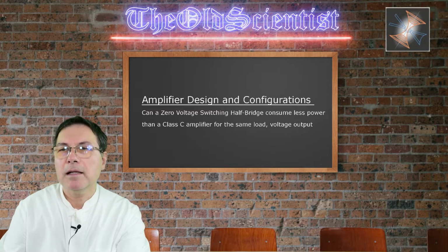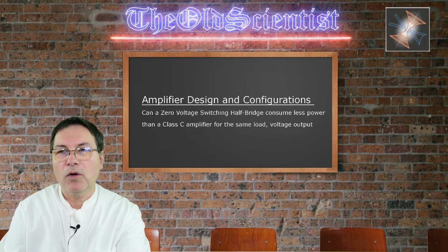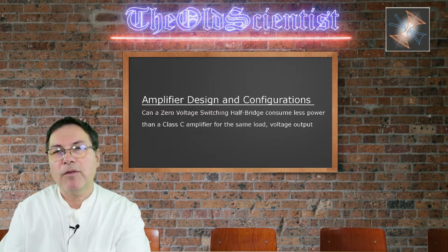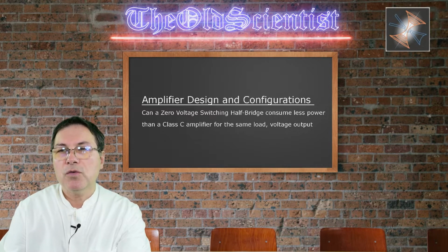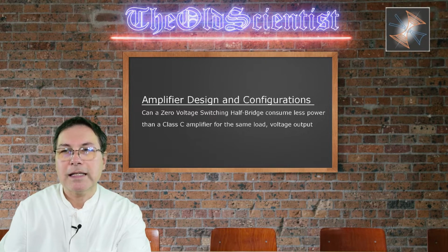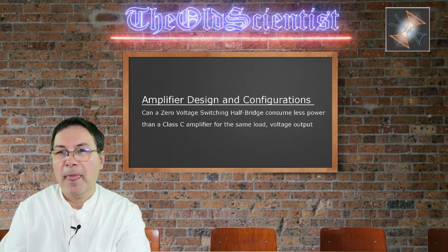Let me explain in more detail. We want to drive a flyback transformer to achieve 18.1 kV on the secondary coil peak to peak. The class C amplifier has one MOSFET and uses only the positive wave signal on the gate. It switches off on the negative gate signal.